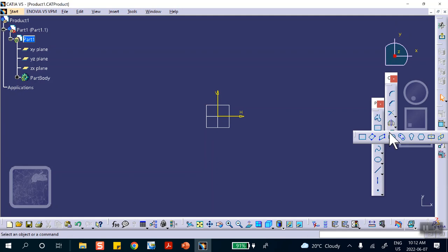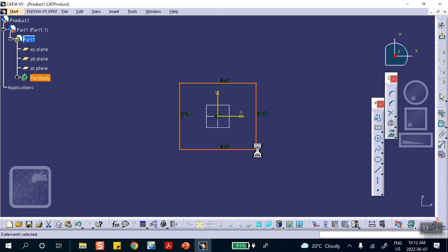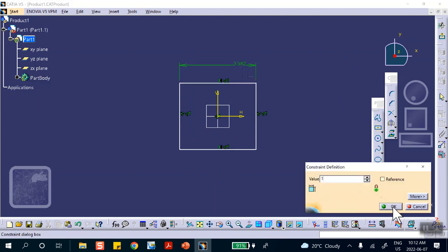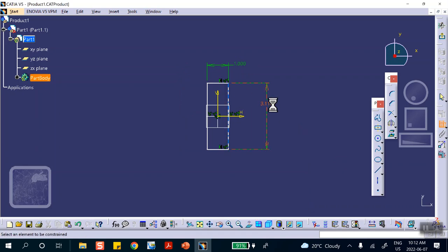It really doesn't matter whether I center it or not. I will because we're not going to cut it anyways, but it's always a good idea to do this. So here, let me dimension these things. So this is 1 inch there, and 1 inch there.